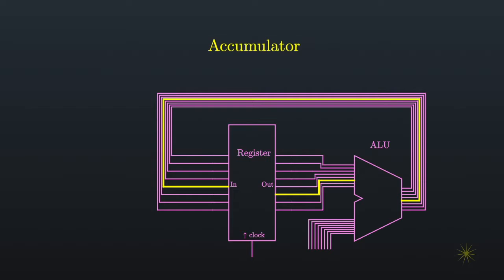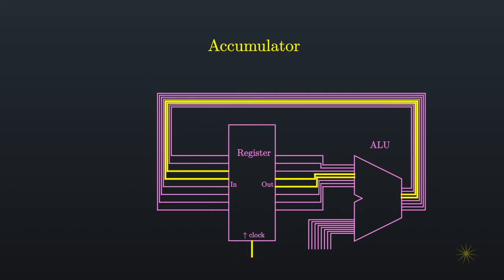Suppose we want to shift the contents of our accumulator. The output of our arithmetic logic unit shows a bit shifted upward by 1 bit position from the output of our register. But now watch what happens when we read the contents. Because we're reading and writing at the same time, things can get a little confusing. The operation may work, or the operation may fail, giving us the wrong results. Reading and writing our results at the same time can be extremely problematic.